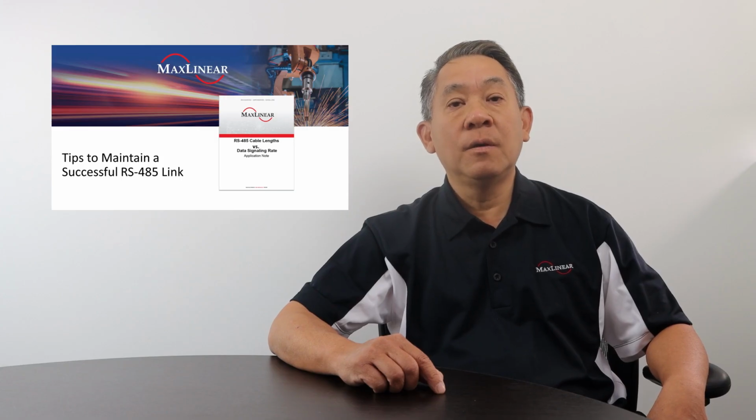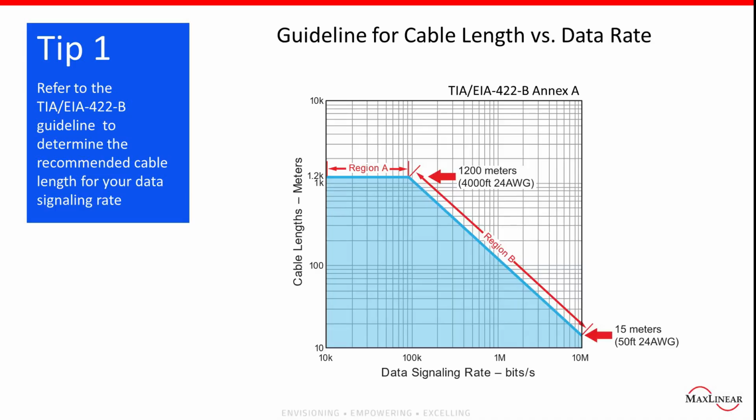In this video, I will provide 4 tips to maintain an RS-485 communication without any data loss. Tip 1. Refer to the TIA/EIA-422-B Annex A for a guideline for cable length versus data rate when designing your RS-485 system. This curve is based on empirical data using a 24 AWG unshielded twisted pair copper conductor with a capacitance of 16 pF per foot and terminated into a 100 ohm resistive load.